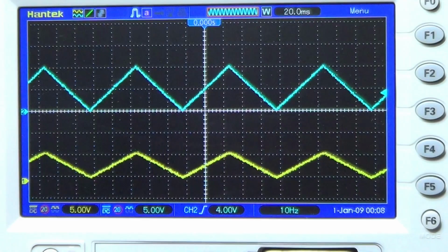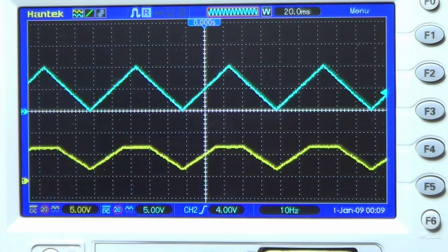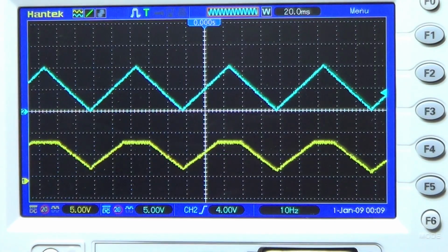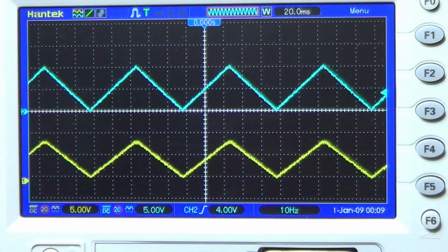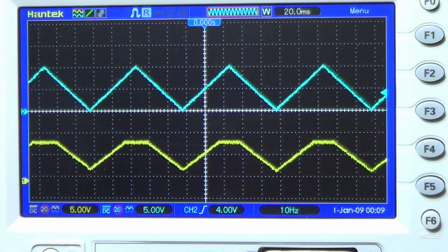But now, if we increase the offset, keeping the DC mixer input controller to the max, we should be able to push the mixer into saturation. Let's see if it works. And yes, you can see how the top of the output signal starts flattening when I increase enough the offset. And of course, I can keep adjusting the controls to increase and decrease the distortion at will.